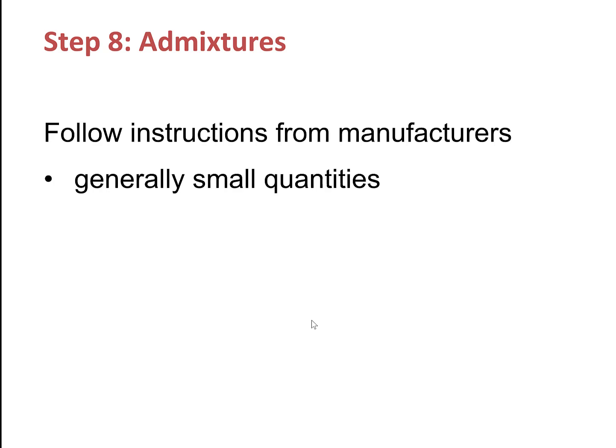In the next step, we will talk about admixtures. So if you are going to use admixtures such as accelerators, retarders, hydration controllers, or water reducers, then you need to follow the instructions from the manufacturers. In general, we need to use very small quantities of admixtures.